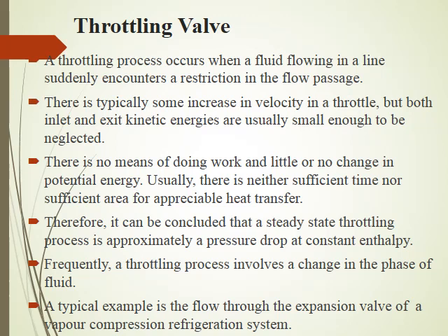In the case of a throttling valve, neither is there sufficient time available, as the process is adiabatic and adiabatic processes are fast processes, nor is there sufficient heat transfer area available. So the process is almost adiabatic. Also, there is no work done, as I have mentioned, and the change in potential energy is negligible.